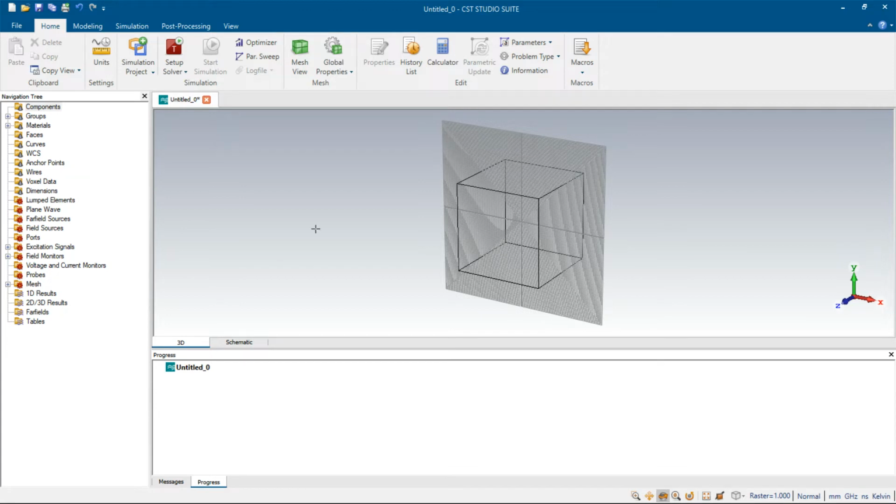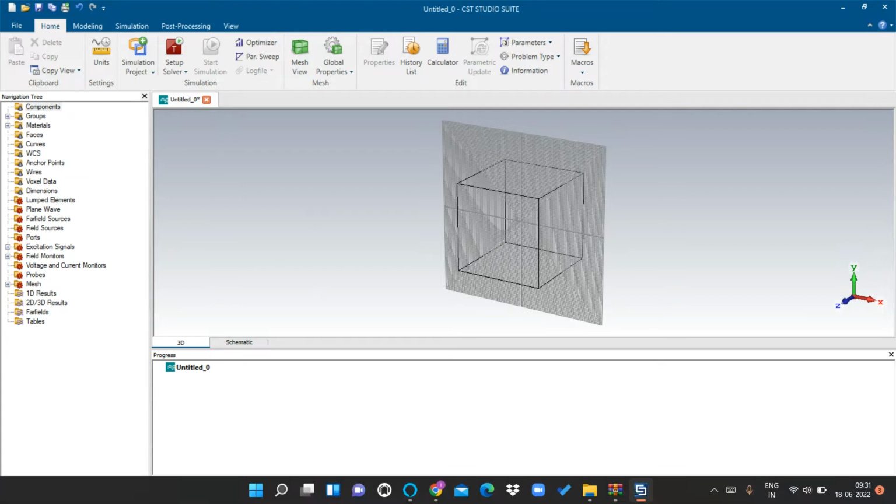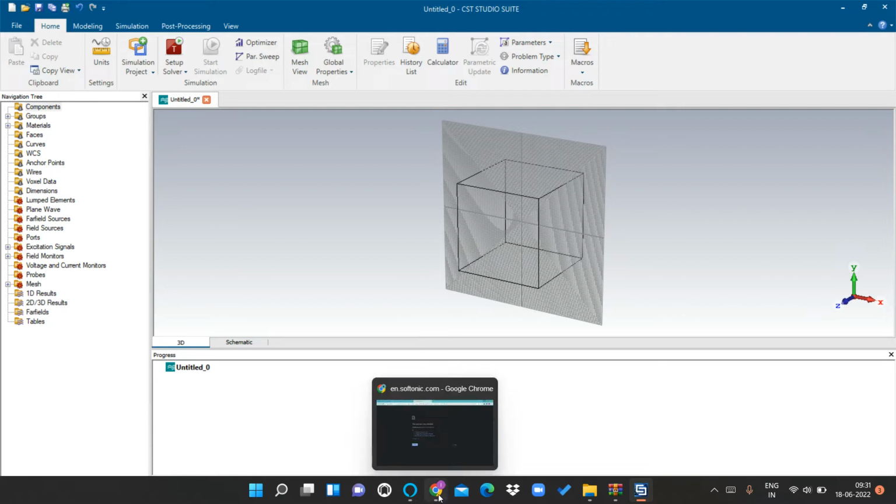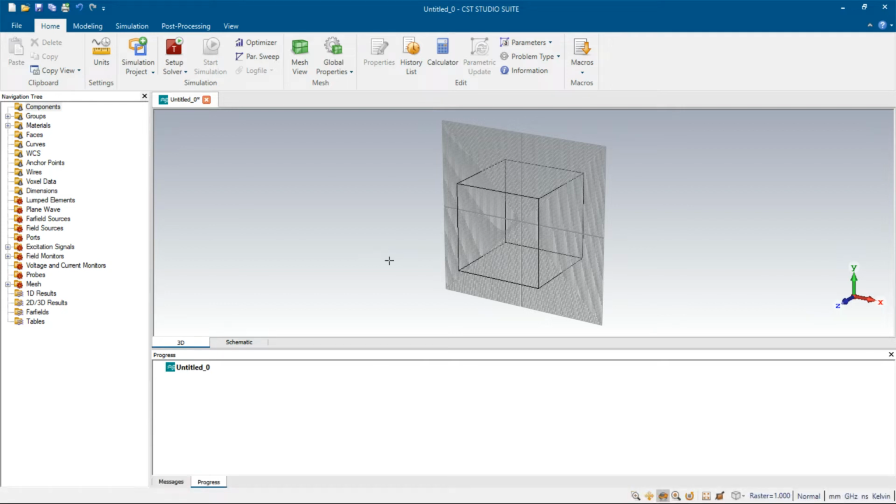And we are designing a microwave patch antenna, so microstrip. A microstrip patch antenna is defined with 3 layers, like a capacitor. Over the 3 layers, ground, substrate and patch layers will be there, where the ground and patch layers are made of pure conductors and the substrate layer is a dielectric. So we have to define 3 layers, and first we will design the ground layer.